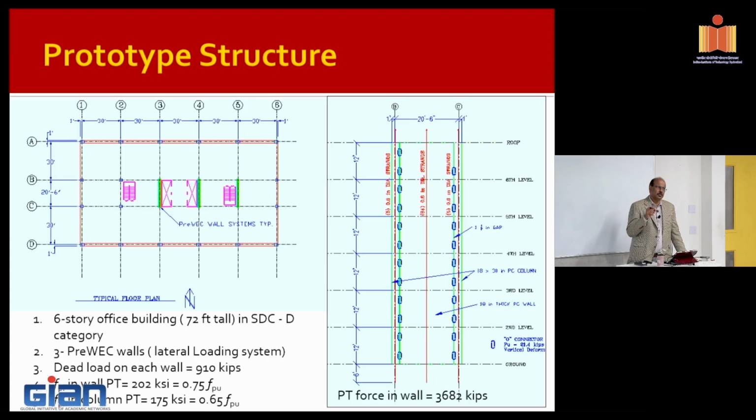So what I want to do for most of this morning is isolate one of the walls, and we're going to detail it in two different fashions. One is with a controlled rocking concept, right? We will have unbonded post-tensioning. That's what we have been promoting. So if you want to emulate, you're not expecting high seismic, you basically design it and put couplers and you have the wall, right? I've already given you a paper on the emulation concept that you can follow.